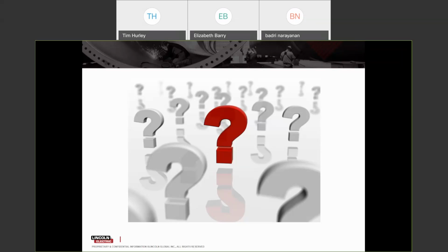That is sort of a higher hurdle or threshold to achieve the silicate formation, because the more CO2 content we have in the gas, the more surface silicates we expect to see. Some of the additional material testing, I'm sure, will include 90-10 gas mixture testing as well, but we just have not pursued that yet, knowing that the 90-10 gas mixture is preferable. We should make it better. We haven't tested that yet.